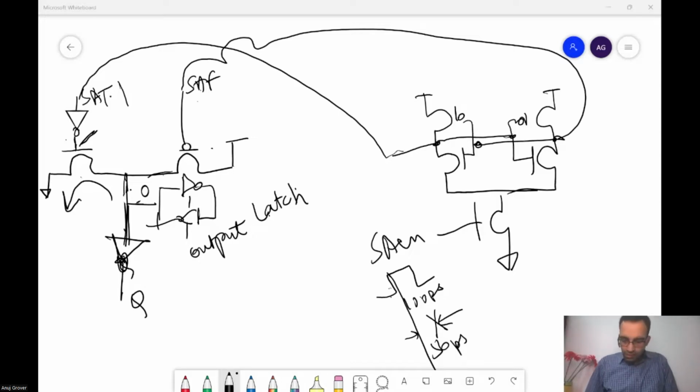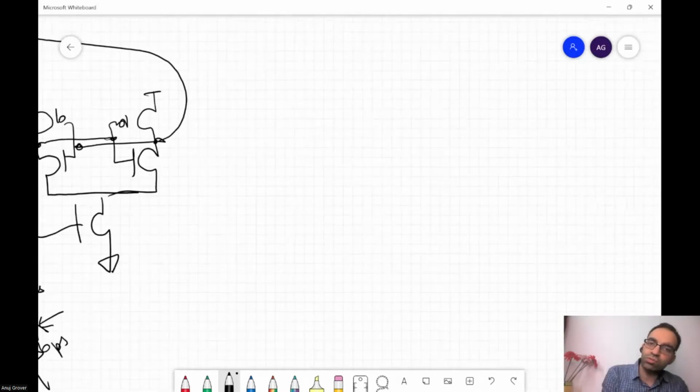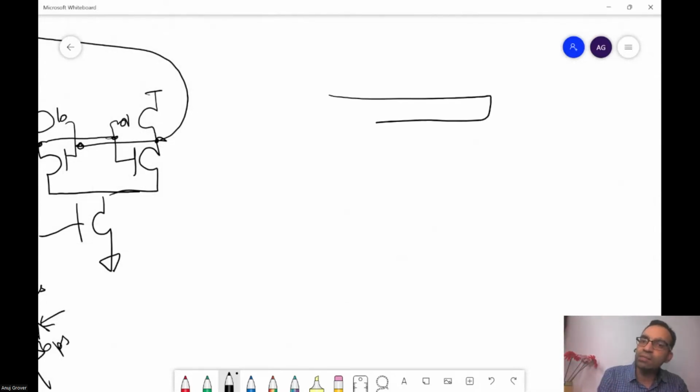But you do it within constraints. Now the sense amplifier width has to be constrained within mux 16, so it depends on how the mux is chosen. The IO group has to work very closely with each other. Suppose the IO group says, okay, I will put the sense amplifier below mux 16. Then the entire mux 16 width is available to you. Suppose the multiplexer team says, just so that the delays are not very high, I will implement mux 16 in 2 phases. One is 4:1, and then another 4:1 stage.